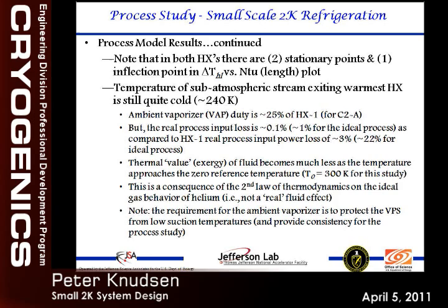Something that's worth mentioning too, the ambient vaporizer that we have is basically taking the flow out of the warmest heat exchanger. Now the flow is going to come out of there fairly cold, and there's actually a good deal of duty on that. But in terms of the actual power loss, it's not a significant contributor to the overall power loss. That's what I'm trying to mention in this part of the slide right here.